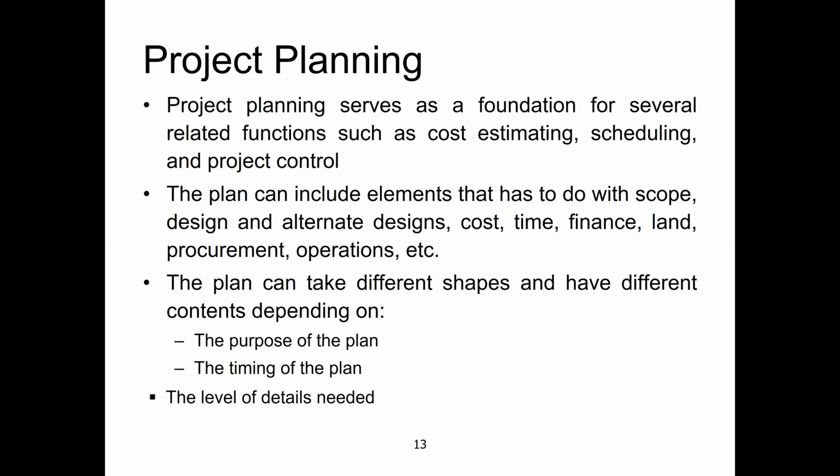Project planning serves as a foundation for several related functions such as cost estimating, scheduling, and project control. Because with project planning there can be a work breakdown structure and work packages. So we know the cost of those work packages that we can sublet to other contractors. So we control costing and even the schedule for those work packages. We control the project cost and even the project completion time. So planning is a very important thing for managing the project.